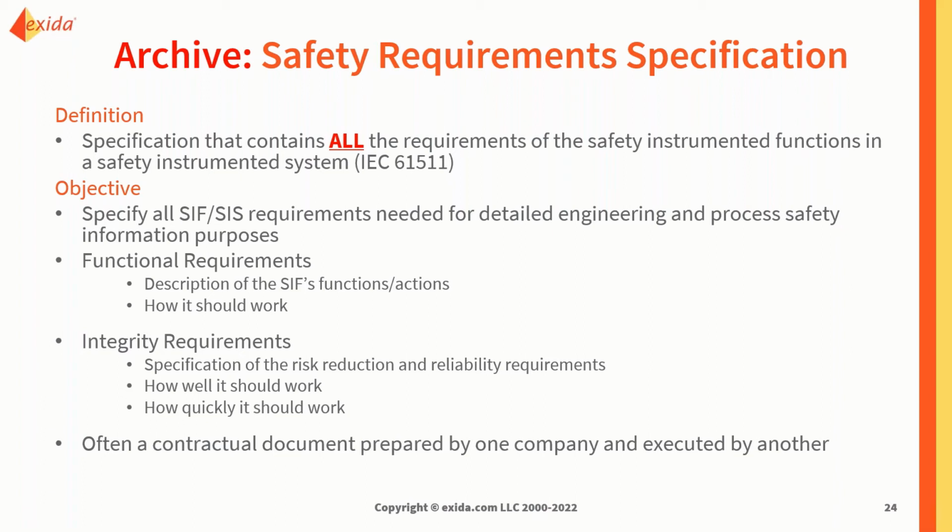And there are also integrity requirements, which are basically related to the SIL level, and also how quickly it should work. What is the process safety time? How quickly do your valves need to be closed? In that case, it can be something related to how you're going to set up your PLCs, or it's going to be related to the instrument that you choose, whether the valve can actually close within that particular time.